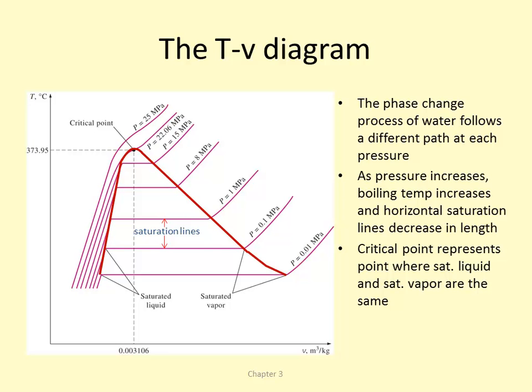Okay, so what's my property here? The difference between the saturated vapor specific volume and the saturated liquid, so it would be Vg minus Vf. If I wanted to determine the distance between here in terms of enthalpy, then it would be Hg minus Hf, or Hfg. So what does Hfg represent in physical terms?